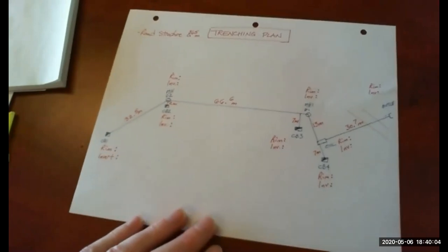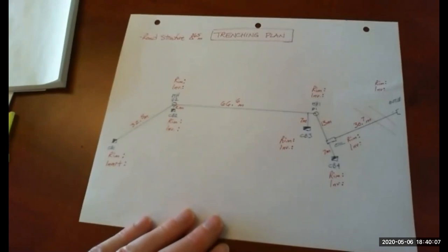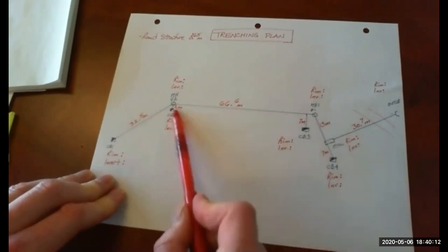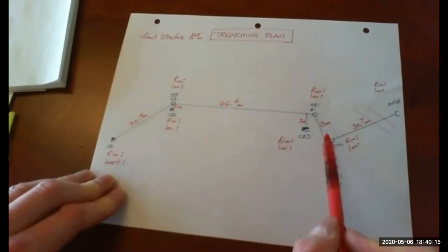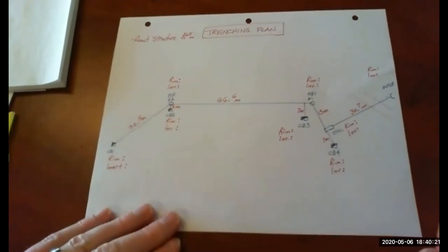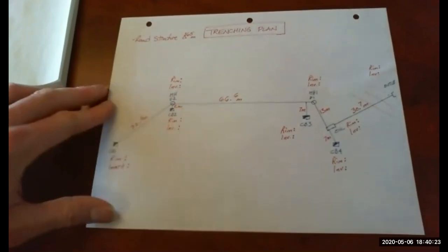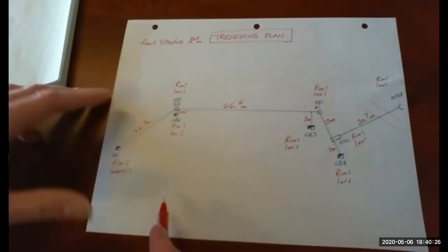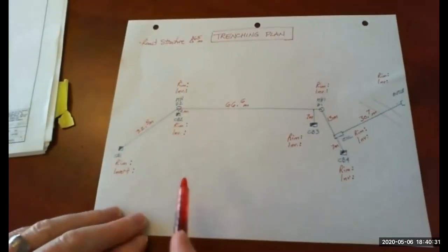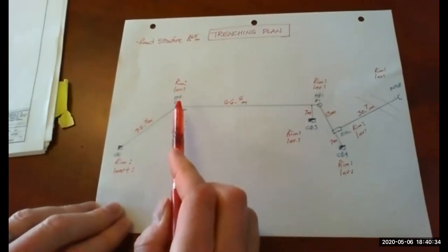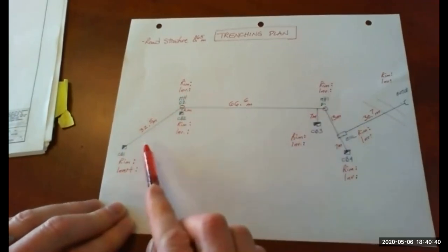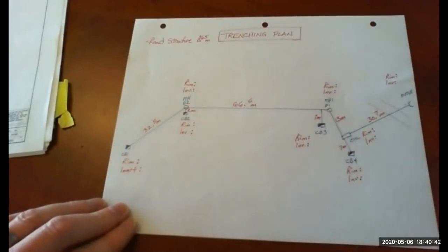Okay, thank you for bringing that up, Andy and Bruno. Where was I? Yes, so we will look at these two sections of pipe in the review of the exercise. I will not look at the rest of the pipe because, again, it's all the same calculation. So the first thing that I'll do here on my sketch is take the relevant information off of my drawings. So I'm looking for rim and invert of CB1, of manhole D2, and of manhole D1. So I'm straight copying off of my drawings.